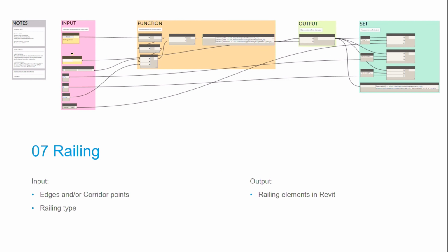Railing is a bit complex to model in Revit without the use of adaptive components. So for the railing part, we used a script that we've developed in the Netherlands. In the Netherlands we have an initiative where all the big firms are joining together to create Dutch standardized components. Those railings are included in them. You can download them for free. They're included in the handout as well, together with the script to place them.